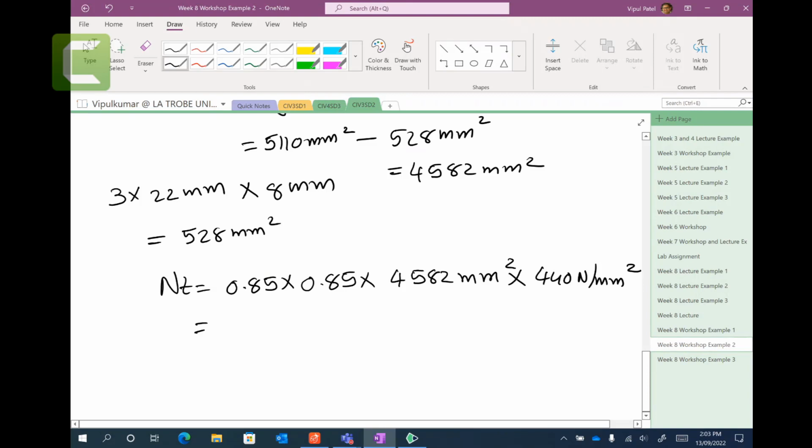So you get 0.85 times 0.85 times 4582 times 440. You get 1456617.8 newtons, which gives me 1456.62 kilonewtons. Right?